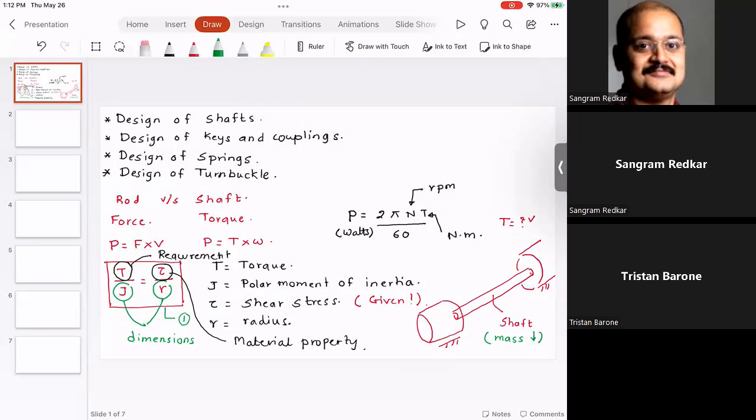So if you want to assume the distributed mass, then the shaft is going to have its own self weight at the CG of the shaft. What that means is, if you were to draw the free body diagram, you have a load at the center span. This is the weight of the shaft, W, at the center span. And what would this load do? This load would deflect the shaft and give rise to bending moment.